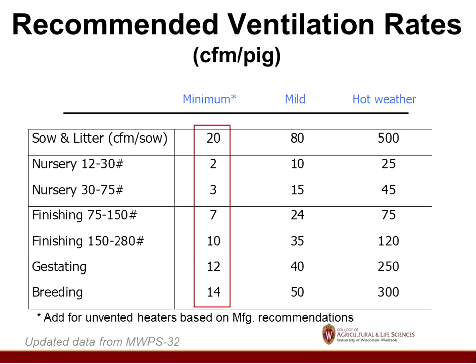Been talking about minimum air quality and stuff. Well, for every species there's a minimum airflow rate that's recommended depending on the species and size. So this would be in very cold weather. When your heat loss is low, this is kind of the minimum you're going to go to. This is where all your heating is going to be required when it's really cold, but you still have to provide some ventilation for air quality. That's usually what hits it in low cold temperatures.